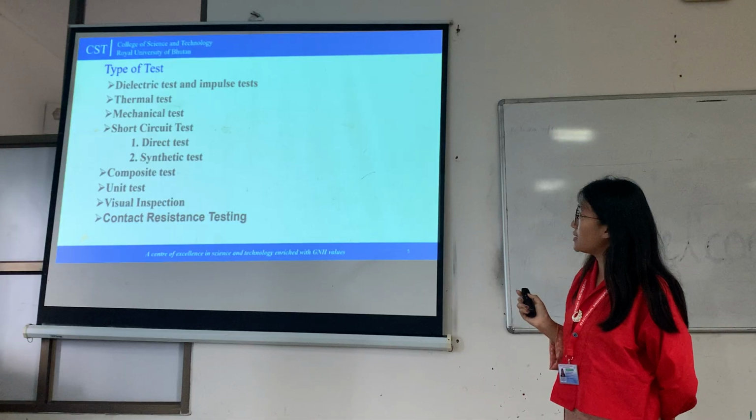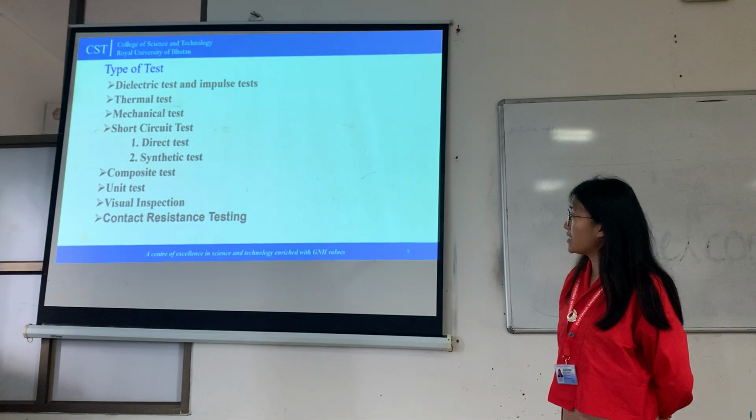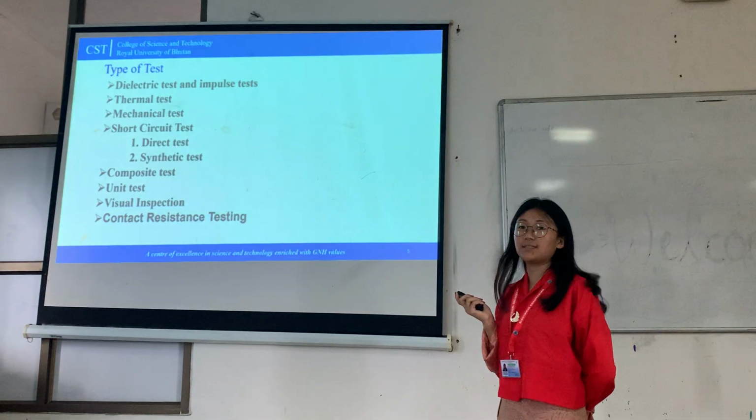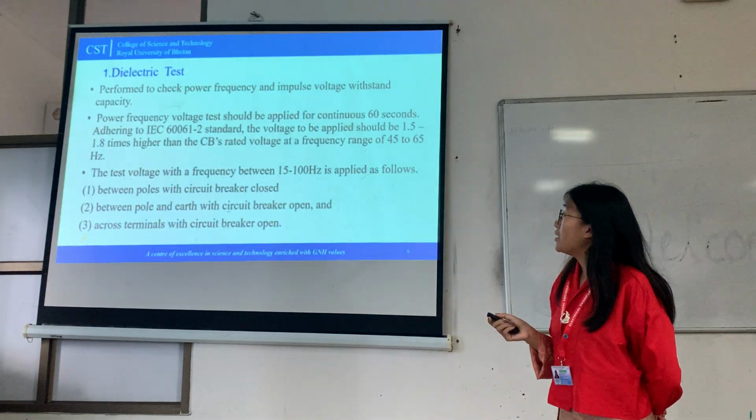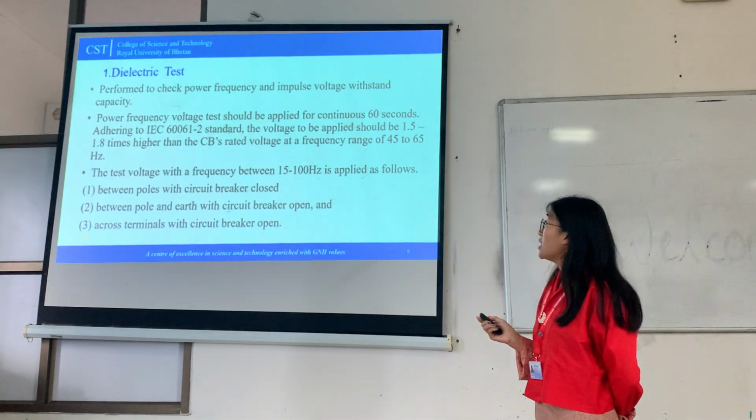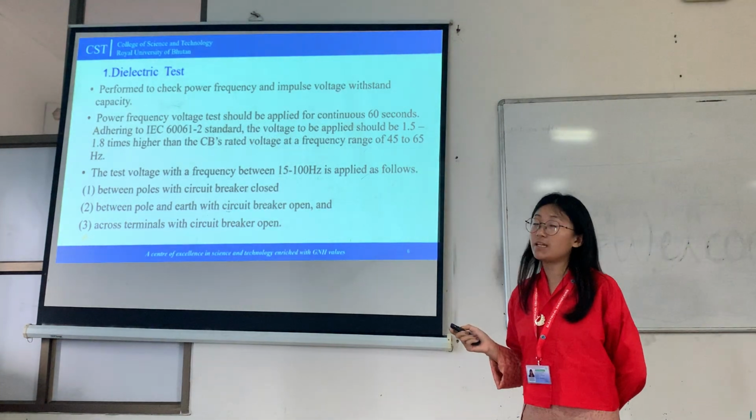Parametric test, dielectric test, thermal test, mechanical test, short circuit test, composite test, unit test, meter test, and contact resistance testing. When it comes to the dielectric test, it is performed to check the power frequency and impulse voltage withstand capacity.